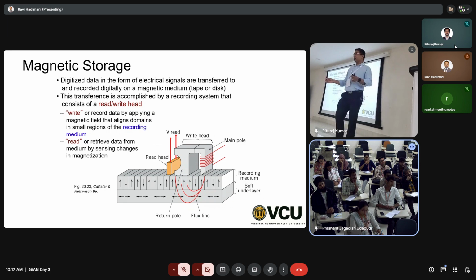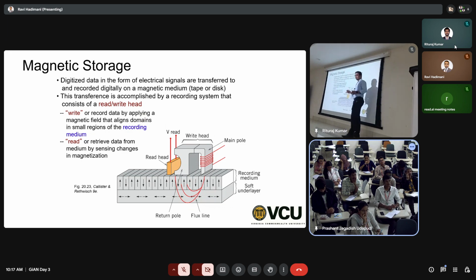But this sensor is built on a phenomenon called giant magnetoresistance. This was discovered by two people, Albert Fert and Peter Grunberg, who simultaneously discovered the phenomenon while looking at the resistance of materials. When they put three magnetic thin films together, they saw that the resistance suddenly jumped up, although all three are conducting materials.